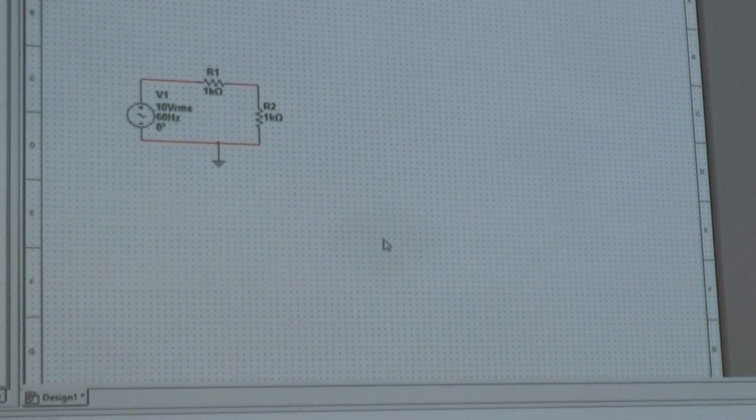Okay, so can we use a multimeter to do this? That's a loaded question. You can. But it will show the RMS. Yeah, that's right. So one of those multimeters there will give you a single value. So if I put 10 volts peak to peak in, and I put it into a multimeter, it's going to try and measure the RMS. In other words, the actual amount of power which is in there, neglecting the fact that it's going up and down. If you don't get that, don't worry, it's not that important.